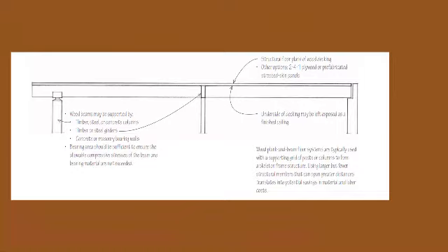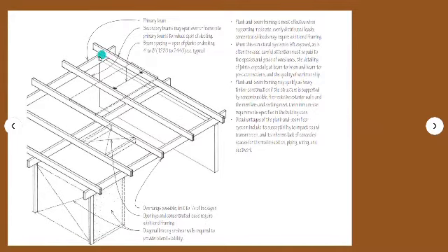Using larger but fewer structural members that can span greater distances translates into potential savings in material and labor costs. And just for this image, we can see just right here, this is the primary beam, and then the secondary beams here, and the secondary beams may span over or frame into primary beams to reduce the span of decking. This is the beam spacing, like the distance between the two beams.